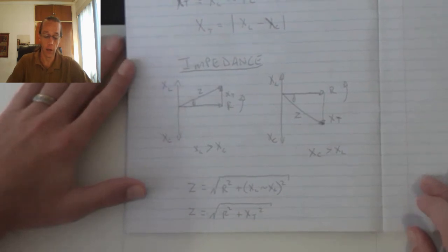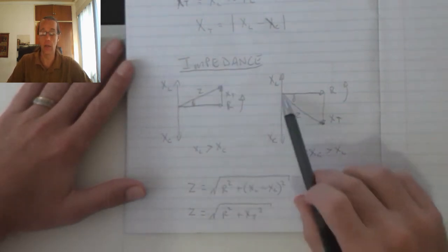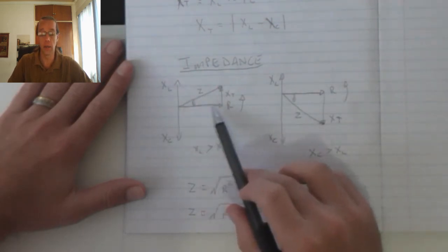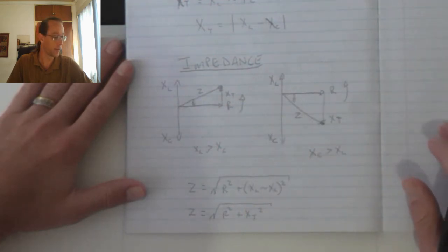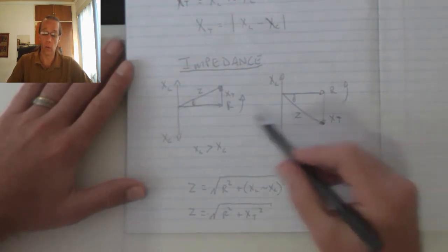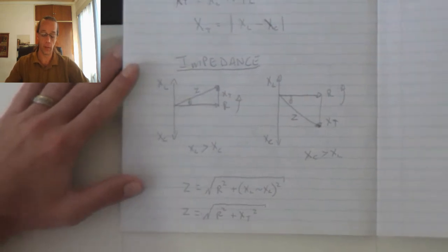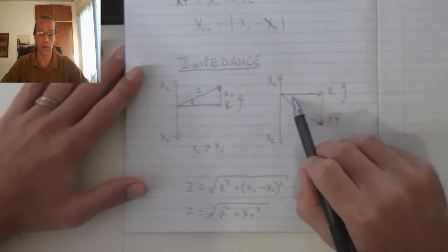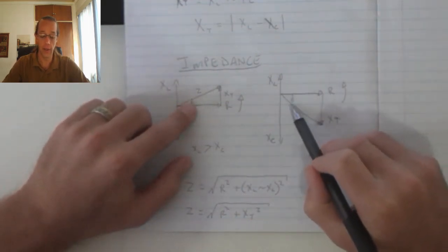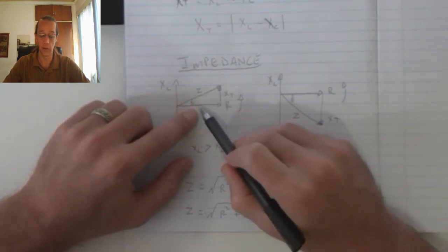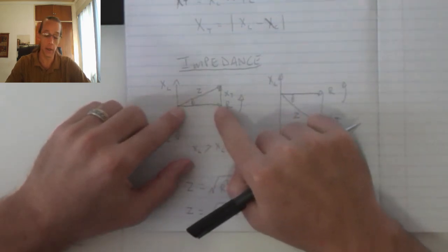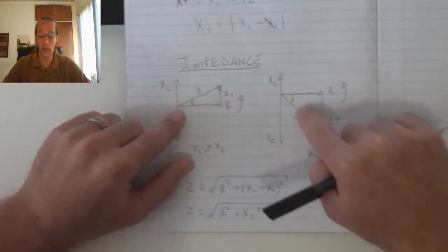These diagrams are called my impedance triangle because we can clearly see that in both cases we are forming the triangle that represents the impedance with reference to my reference, which is the resistor. Now, that specific angle, in both scenarios, is called my phase angle. If I convert these diagrams to a phasor diagram, I will see that the current is on the horizontal axis and the voltage is in phase with my impedance.